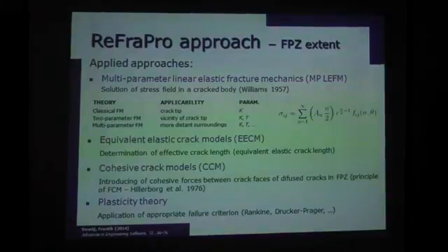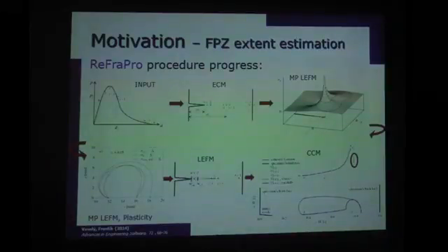So for that we adopted our approach, within which multi-parameter fracture mechanics plays a very important role, and I will focus in this talk on the multi-parameter description of the stress field in order to be able to estimate the size of the process zone, which is sketched here in this slide.